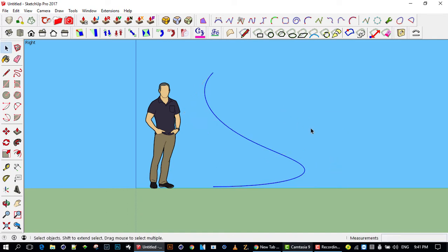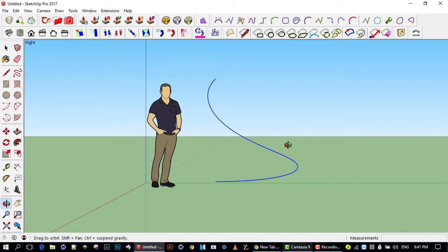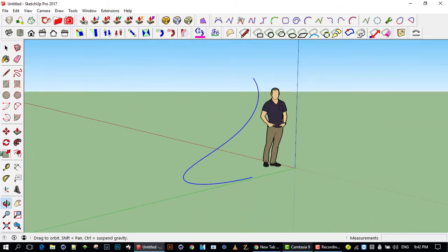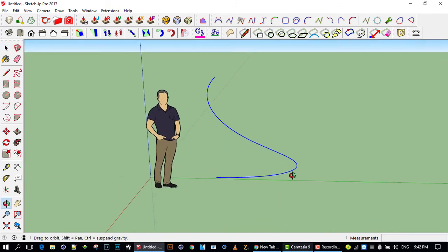When I click off it, I'm going to go out of the view now, and you'll see that's what I've created over there. So that's how you can use one of the tools. It's quite great being able to create these Bezier curves, but also edit them and smooth them. It just takes a bit of getting used to these different tools, and you'll get to use one or two of them, probably more than others. But this is when you're creating things that you want to create lofts and that sort of thing with.